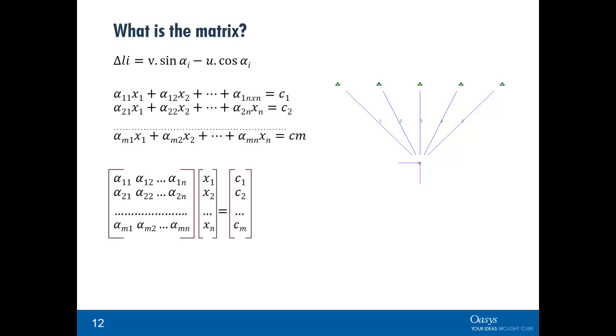For example, putting something of zero stiffness in there means you've got a line in there with zeros in, which means you're going to get divide by zero errors at some point. Likewise, a bar element has limited degrees of freedom. So a beam will have 6 degrees of freedom, a bar will have 3.